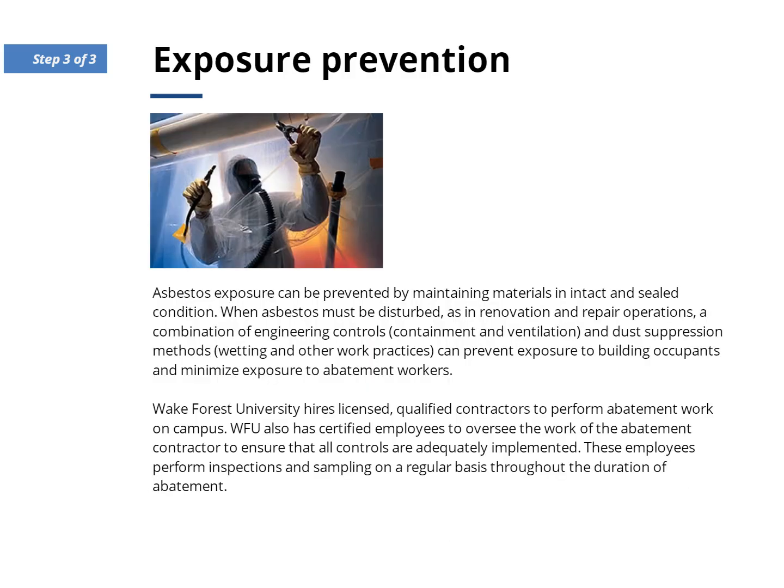Asbestos exposure prevention. Asbestos exposure can be prevented by maintaining materials in intact and sealed condition. When asbestos must be disturbed, as in renovation and repair operations, a combination of engineering controls, containment and ventilation, and dust suppression methods, wetting, and other work practices can prevent exposure to building occupants and minimize exposure to abatement workers.